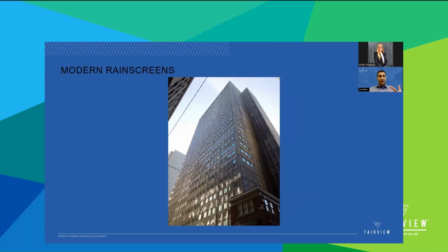Moving forward, it is in the 1940s that further research concluded that using rainscreen cladding was the best option for exterior wall assemblies, because walls constructed of porous materials will eventually crumble if exposed to moist weather conditions for an extended time without being protected by water repellent. Covering these porous materials with an impervious product will result in ideal conditions for mold and mildew, so there had to be a path for water to escape and moisture to evaporate. With the rainscreen, the moisture evaporates due to natural convection in the air cavity between the rainscreen and the substrate.